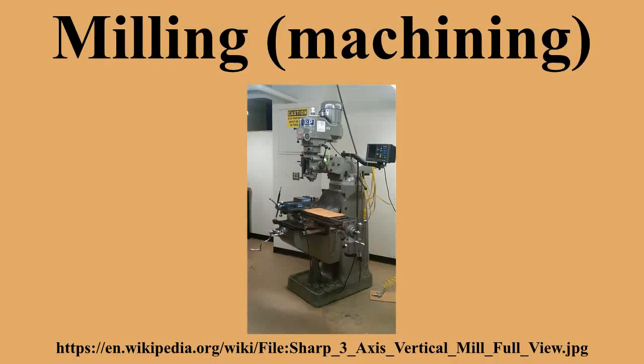In peripheral milling, the cutting action occurs primarily along the circumference of the cutter, so that the cross-section of the milled surface ends up receiving the shape of the cutter. In this case, the blades of the cutter can be seen as scooping out material from the workpiece. Peripheral milling is well suited to the cutting of deep slots, threads, and gear teeth.